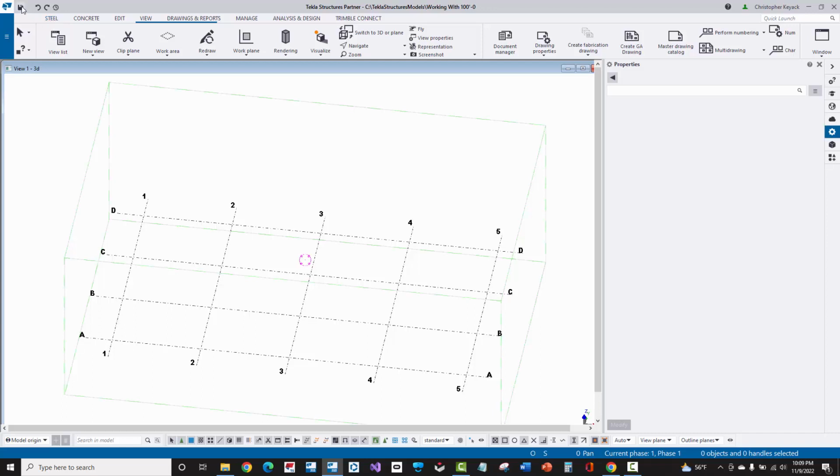Now, if we start to move across the top of Tekla, the other most important thing at the upper left-hand corner is a save button, which looks like a floppy disk. Whenever you hover over these shortcut icons, it'll show you the keyboard shortcuts. So Control plus S, which is pretty standard for save, will save the model. Then we have the undo and redo buttons here, and then we have the undo history.